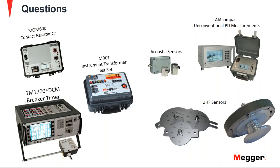It doesn't give you the exact timing of the contact, but it's very close, and it's used commonly as a technique to measure the operating time of the contacts, or to have a close measurement or idea of what is the timing of the breaker. And it definitely can be used on GIS as well. It's used for any type of breaker, high voltage breaker, and definitely can be used for GIS.